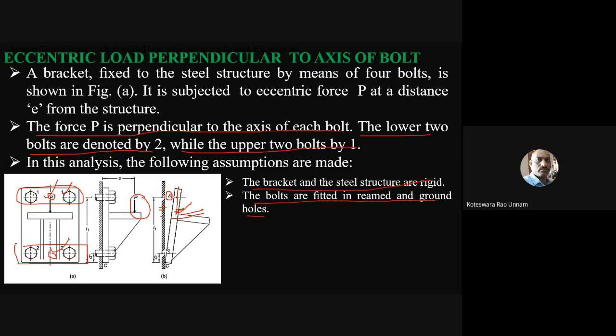Whatever connection we are making here, there is some preparation for that. So the bolts are fitted in reamed and ground holes, and the holes are prepared using this process. The advantage of using this assumption is to neglect the stress concentration. So when bolts and bolt holes are reamed and ground, you can ignore the stress concentration.